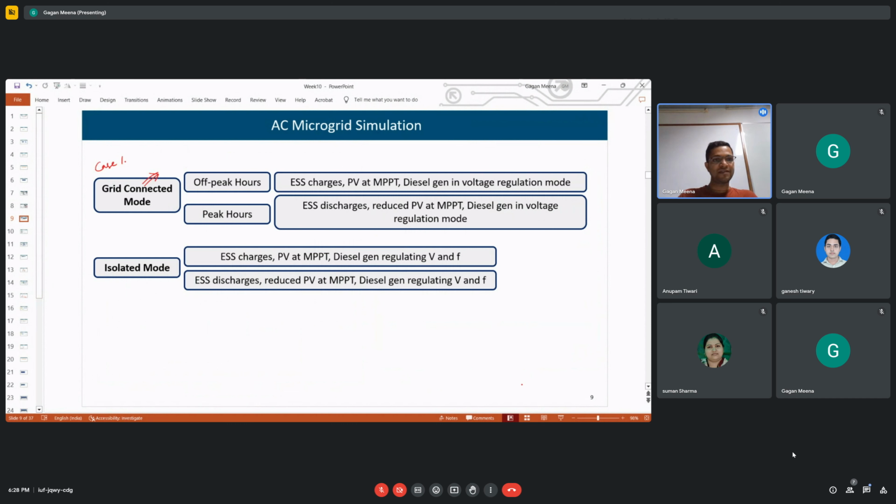Why are we using this high frequency transformer? Because this dual active bridge has certain advantages. First, it provides galvanic isolation because of this transformer. In a transformer, the primary and secondary sides are not electrically connected. If we take this single phase transformer, this is a magnetic core.